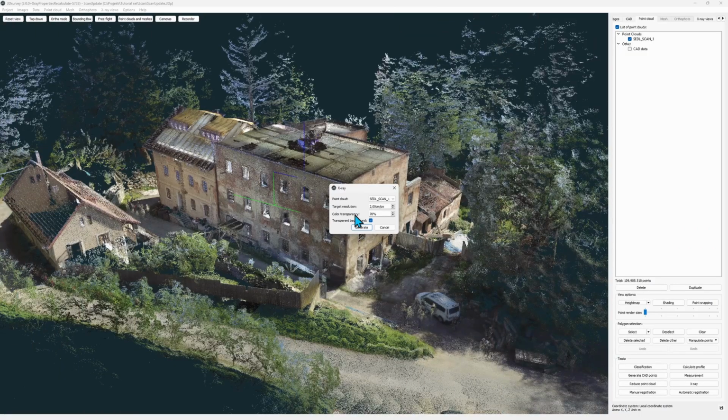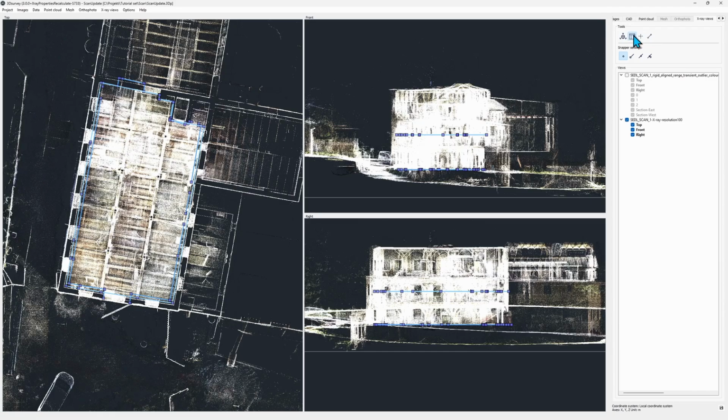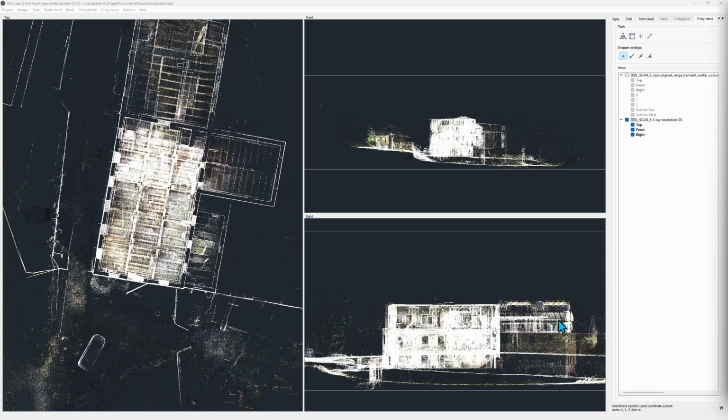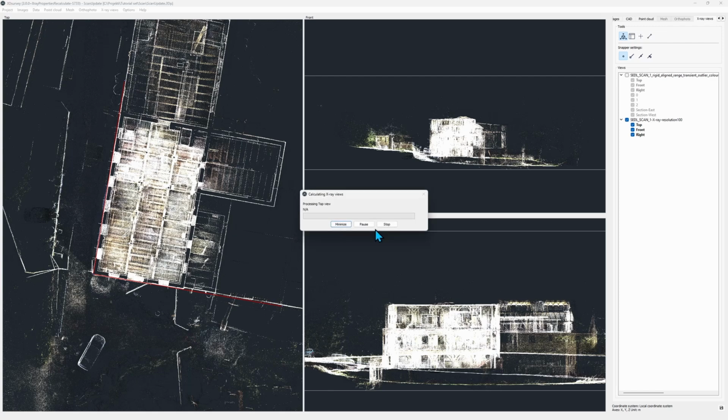The first thing we did was make everything a bit more efficient, so the whole X-ray views bundle is now calculated faster. Also, the buttons are more responsive. Now let's consider these X-ray views. They look sort of okay. The first thing I've got to do is alignment. I select this tool here and just align my walls with this perpendicular axis. And now my X-ray views are recalculated.